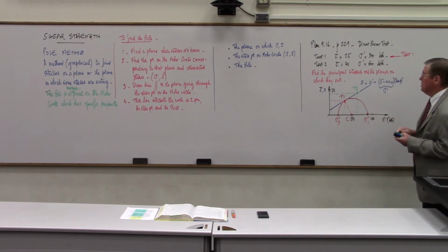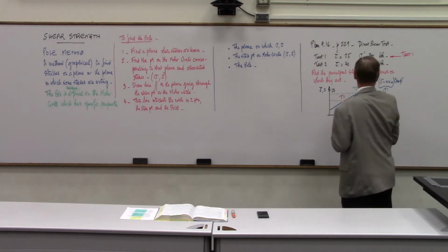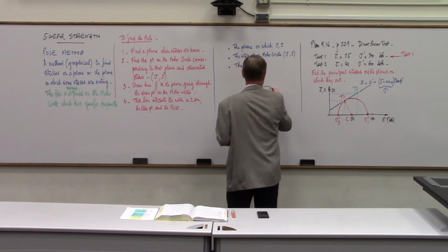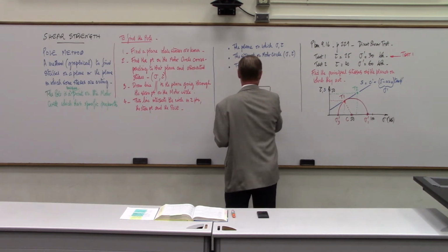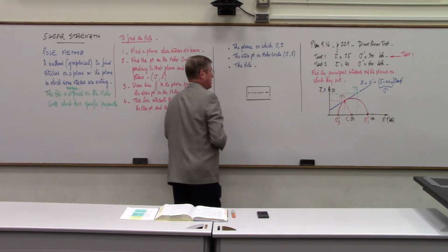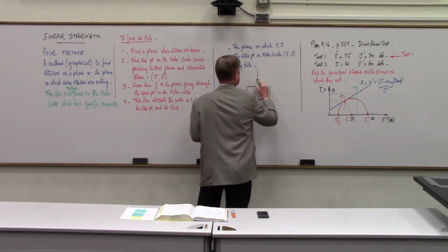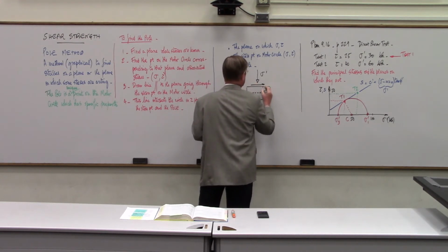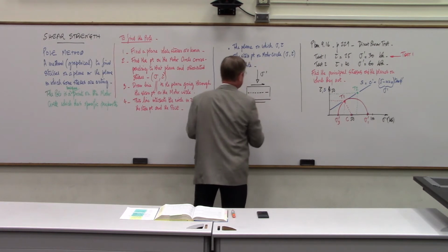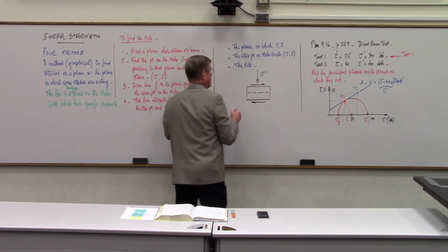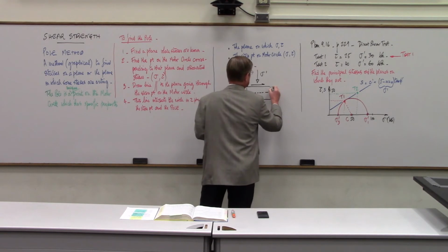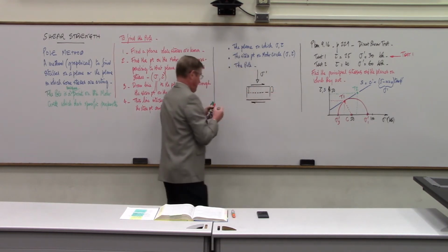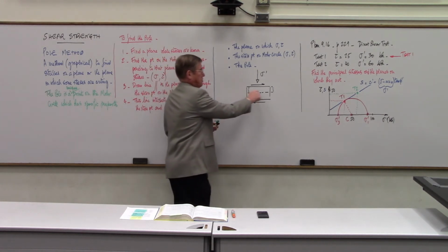In the direct shear test, remember that that test, I'll draw it here, that test is like this, and then we have a shear plane in the middle. We apply sigma prime this way, and then we push in one direction, we resist in the other direction, and that's how we shear the sample, and in this case, the sample would move in this fashion. And the plane of failure is right here.